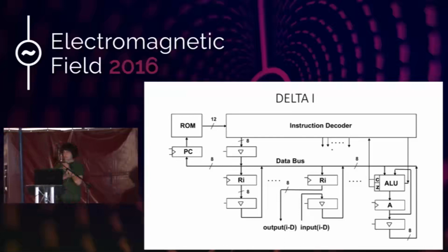And then next to that, we have input and output registers. And these are very similar to the original registers. But instead of putting their own value back onto the data bus, now they have signals going out and in to the processor. So what you could do is you could, for example, connect LEDs to the outputs. And then you could see what value the processor stored to that register. And you can also add switches to the microprocessor so that you can dial in the number and then read from those switches and put that value on the data bus.